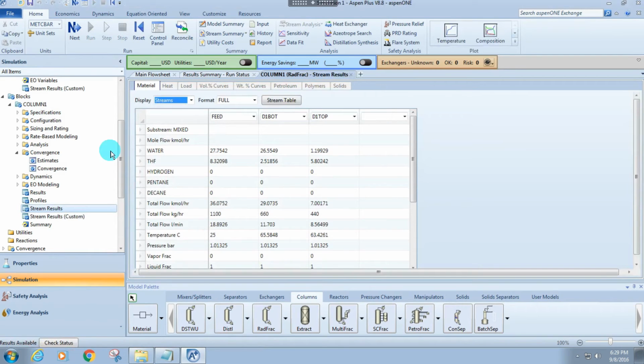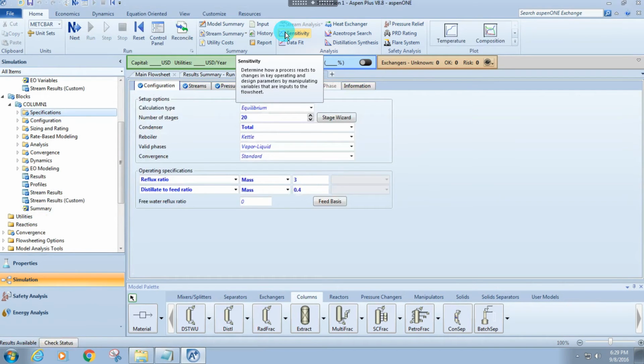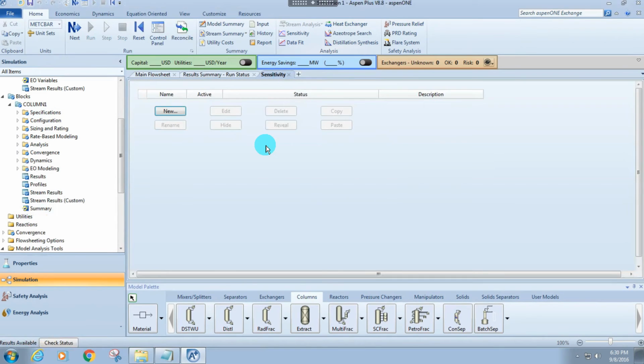So instead of playing the guess and check trial and error of these input specifications, we can use sensitivity to save your time. And I think my section's homework TA went over sensitivity with our class at least. Okay. So sensitivity allows us to vary parameters for us. It's kind of like the for loop in MATLAB, right?